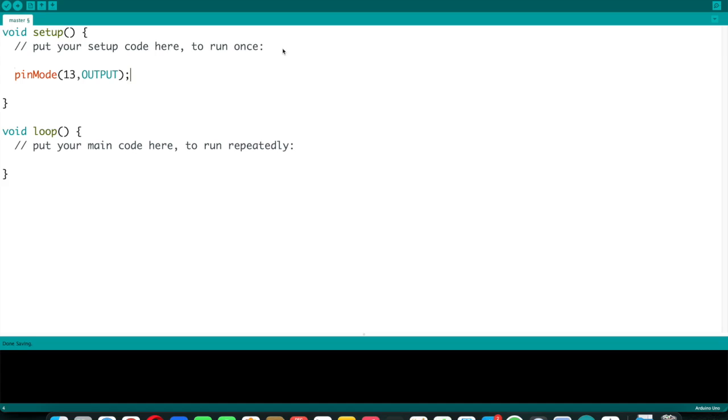It is not the pin number of the Atmega microcontroller. I do not know which port and which pin inside the port pin 13 actually maps to. You need to refer to the data sheet, always refer to the data sheet, to know the mapping of pin 13 to which port and which pin inside the Atmega. However, this number, 13, is the number present on the Arduino board.